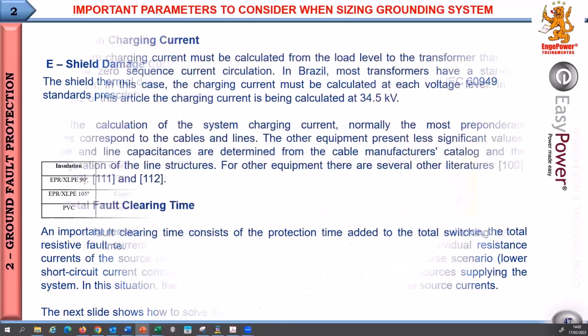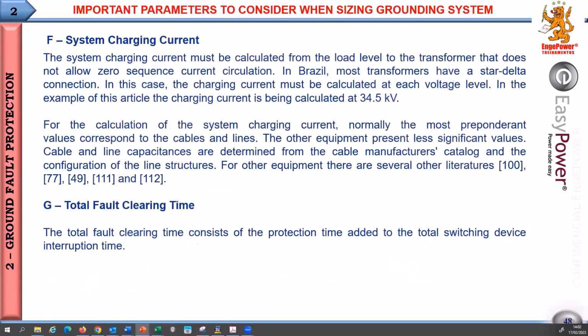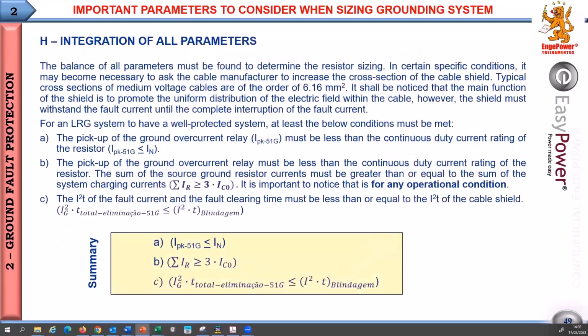Okay? System charging current can be calculated as we showed before, and the total fault clearing time can be set based on all of this we talked about. All these parameters we talk about have to be integrated in order to provide a good design.